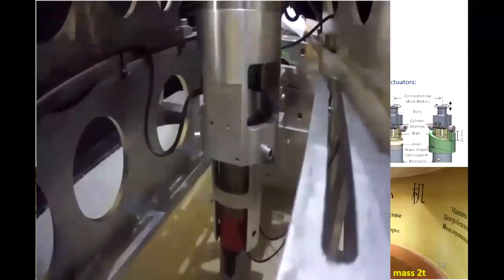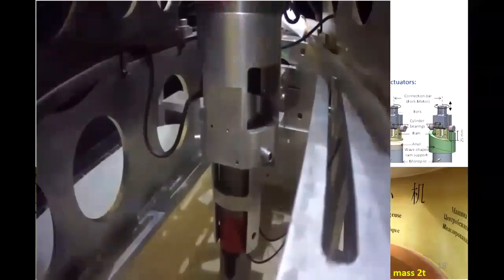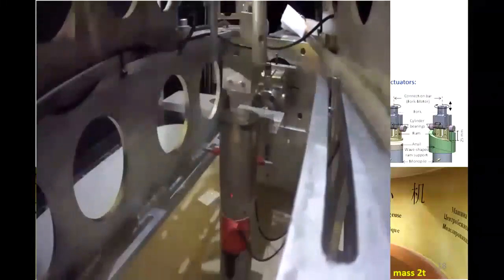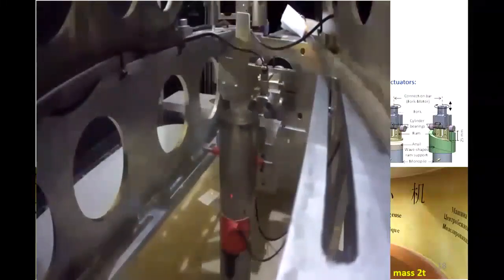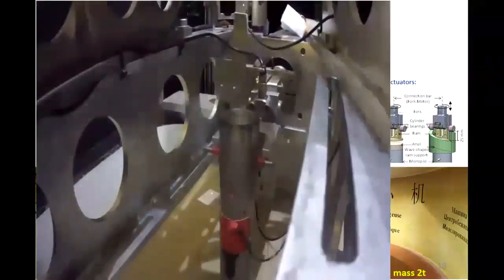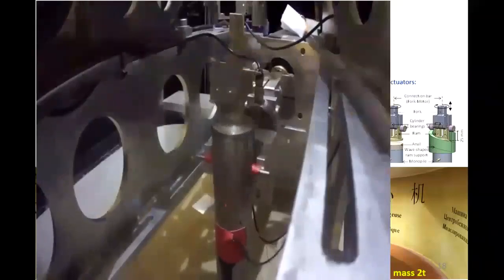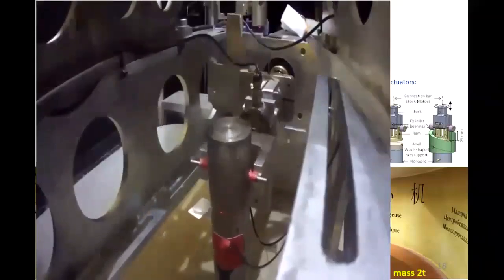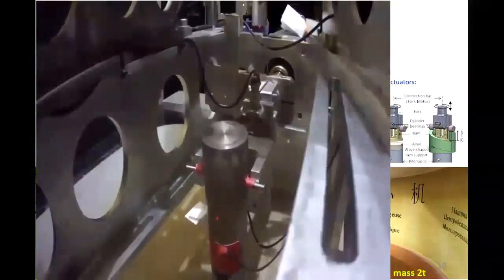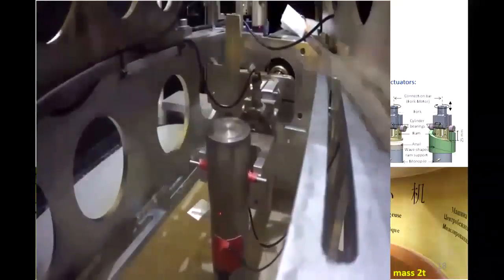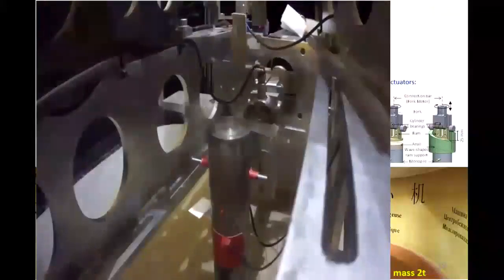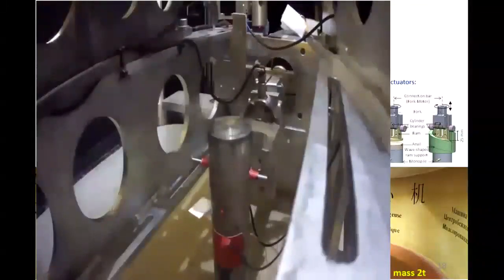And then in this case, we wanted to study the lateral behavior of monopiles. So there is a second jack, an electric jack, moving horizontally, located to apply the load exactly on the horizontal rod that you can see in red, to study the behavior of the pile. So we perform monotonic and also cyclic loading in this case.